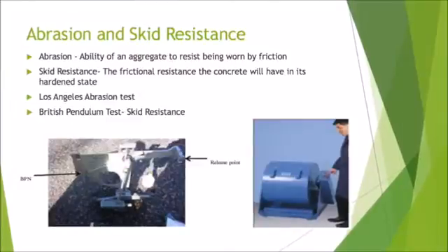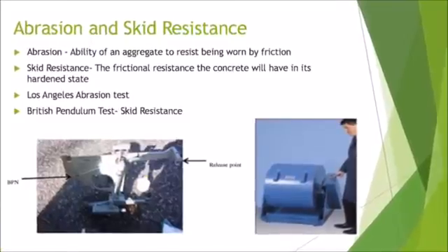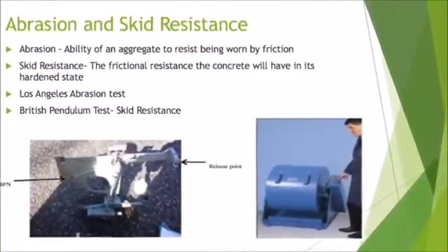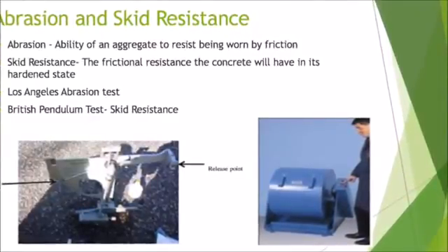Abrasion is the ability of the concrete to resist wear by friction. Skid resistance is what the concrete will have in its hardened state. On the left, the British pendulum test. The Los Angeles abrasion test is shown on the right-hand side.